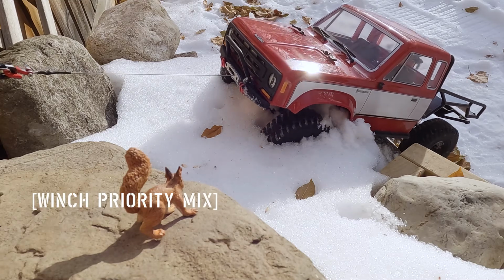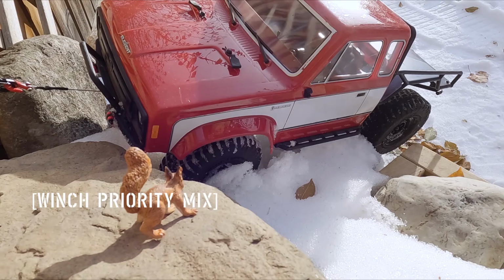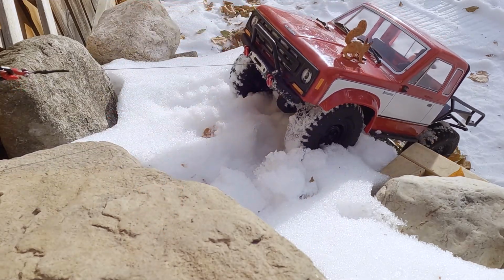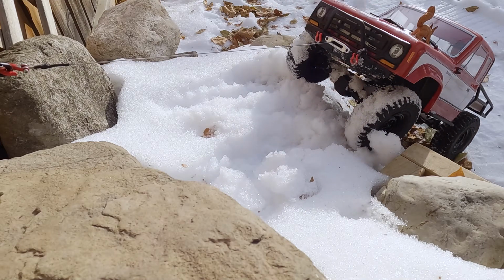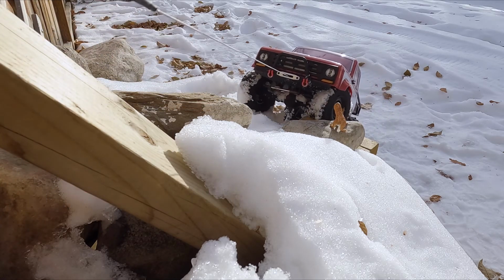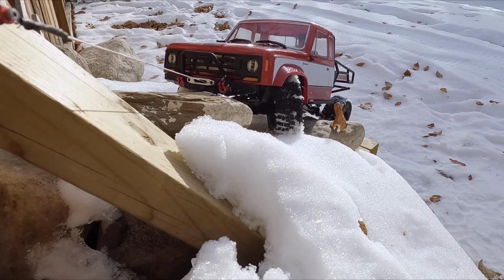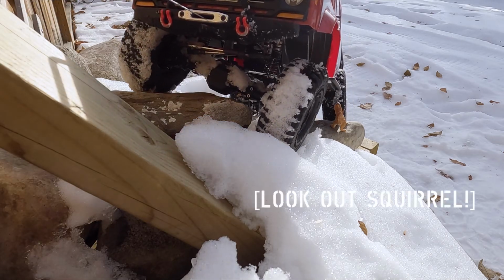In throttle priority mixing, as seen in the previous video, the winch speed is proportional and varies with the throttle. In winch priority mixing, both the winch and wheel speeds are fixed, though the trigger can be feathered to speed up or slow down the wheels. With winch priority mixing, the winch is always pulling at full speed. This might mean less control for the casual driver, but may also be a decided advantage in a competition scenario. You can decide which mode works best for you.